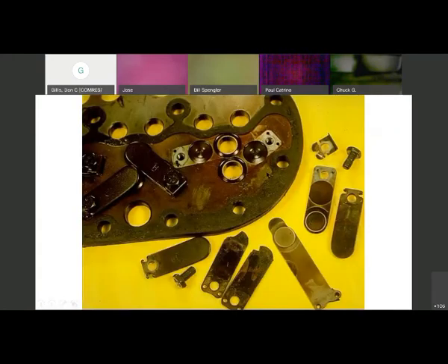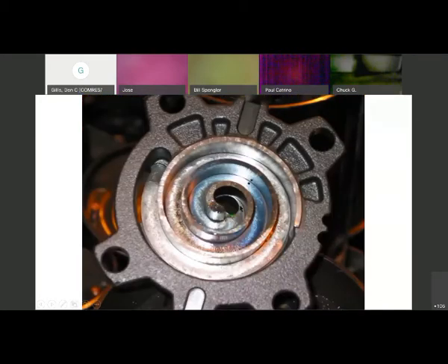This is just an example of what that looks like. You can see the valve cover here. You can see how somebody ran their thumbprint over there and knocked off that tarnish. These are cantilever backers, the sole purpose to support that stainless steel reed valve there. You can see the indentation there, how hot that got. So this got pretty hot. I kept this one in there because I think it's a nice slide. You notice the discoloration, the blue here, and we all know what that means. That got very hot. Again, this is the fixed scroll at the top of this scroll compressor.